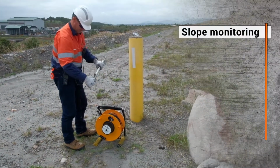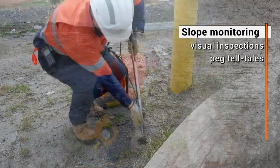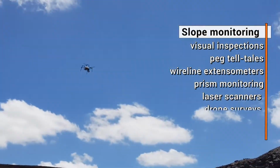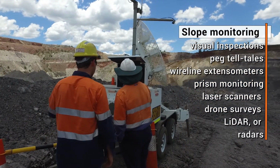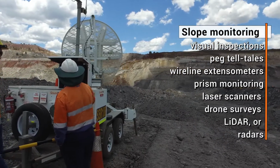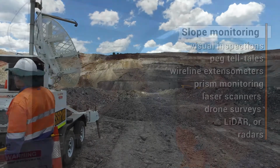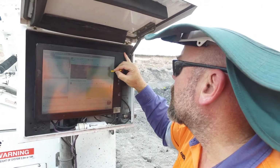Slope monitoring is completed by one or more of the following methods: visual inspections, peg telltales, wireline extensometers, prism monitoring, laser scanners, drone surveys, LiDAR or slope monitoring radars. Monitoring devices can be used for either long-term, broad-scale detection of slope movement or targeted monitoring of a specific area of concern. Regardless of the monitoring device implemented, it is important to remember the following.